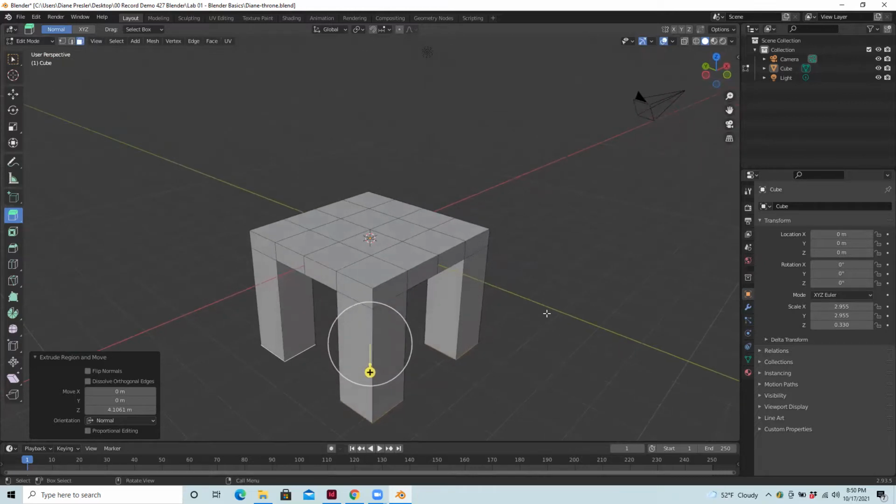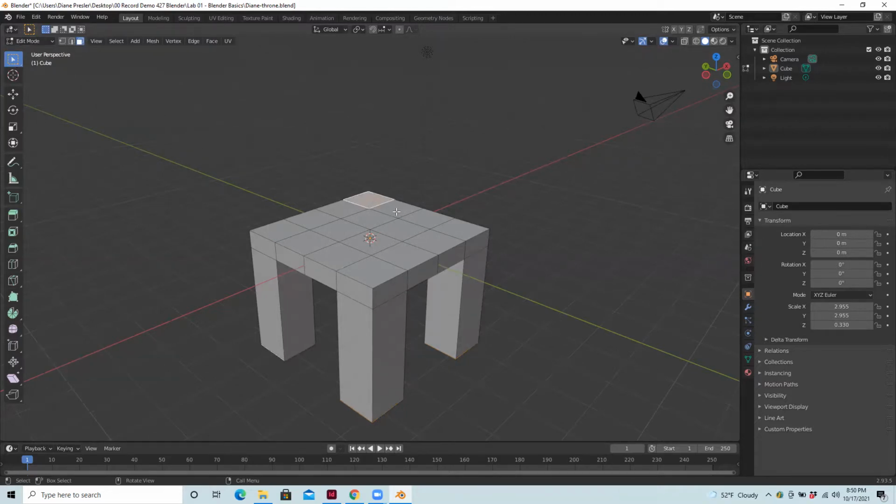I also want to create a backing to the chair. So I think I'll do something similar and select more faces and extrude them to create the back. So let me switch to select tool, double checking I'm in edit mode, and select face. And then I'll click and shift click to get all 4 pieces selected back here.